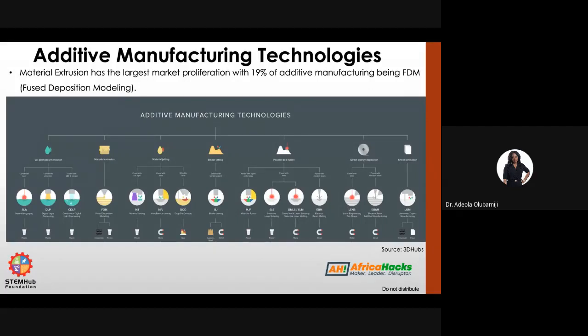You can get 7 PhDs in 3D printing if you want, because there are so many different new technologies out there. If you look at the picture very well, the last part of the picture shows you what type of material each of these technologies can print. So for VAT polymerization, it is used for plastic, because we are talking about resin being cured by UV light. Resin is usually a chemical compound, and then you shine light and form a plastic. So that's a strictly plastic related process.